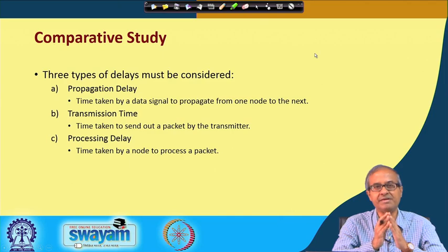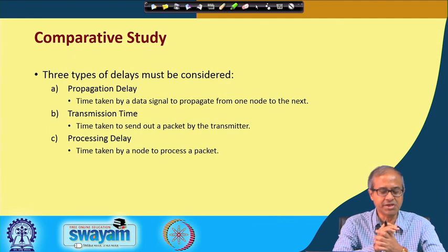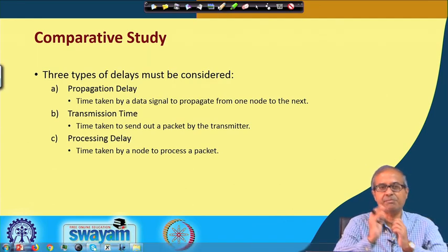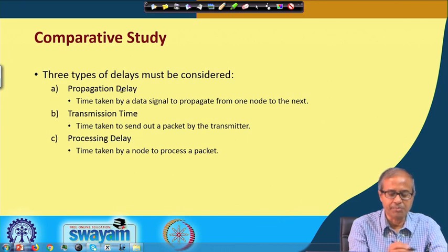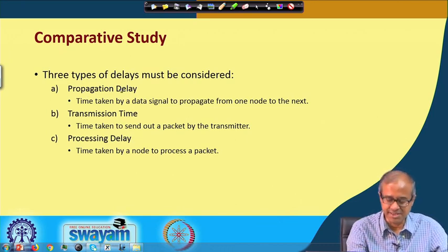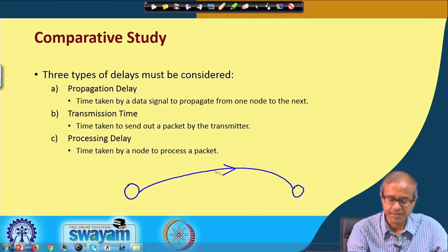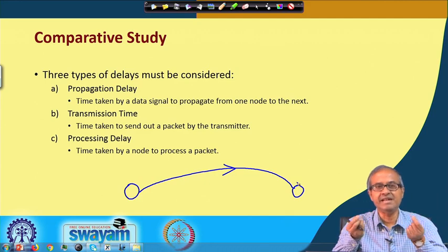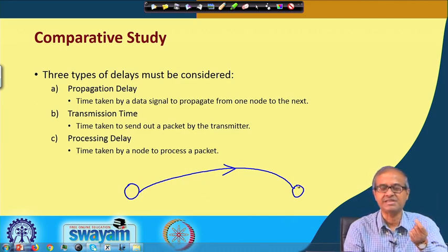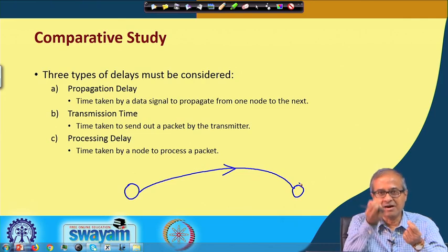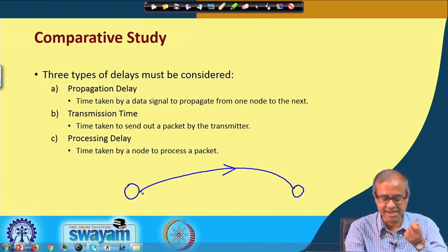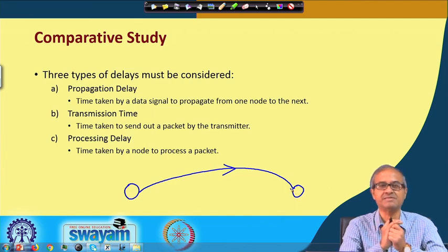Now, if we just compare these approaches which we have talked about, for comparison we usually compare with respect to some parameters. One is called propagation delay. Like you see, when we talk about a communication between two nodes, propagation delay is the signal delay from source to destination. How much time a single signal transition takes to move from this place to this place.